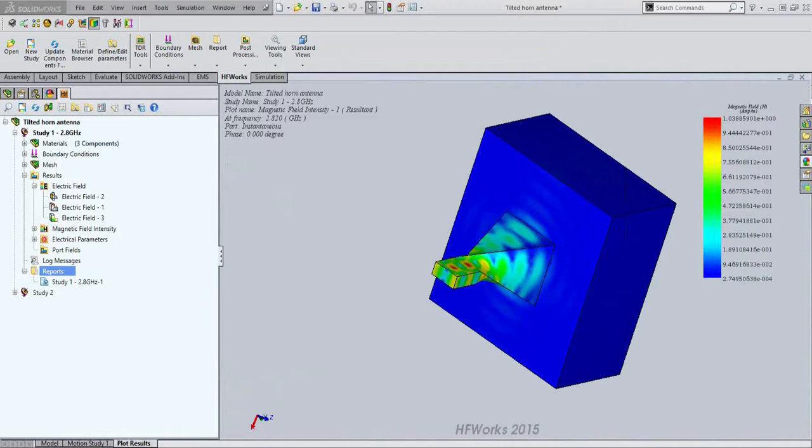So again, as I showed earlier, the process is doing studies. In this case, it's an S parameter study. If I look at the properties of this S parameter study, I can see what we've done. So we've essentially done a fast frequency sweep between 2 and 3.5 gigahertz, and we've done 300 points. Okay, and that's how we solved it. That's our list of frequency points and so on.